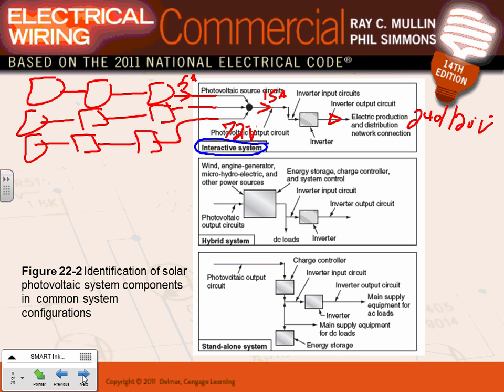Each one of these panels, guys, is, just as an example, 24 volt at 5 amps. This string here can give me 72 volt at 5 amps. Each one of these strings, when you add them up here with the diodes and the fuses, they end up with 15 amps at 72 volt. When you go through the inverter, it inverts it back into 240 at the right voltage, at the right amps. Any questions, guys, about utility interactive system?